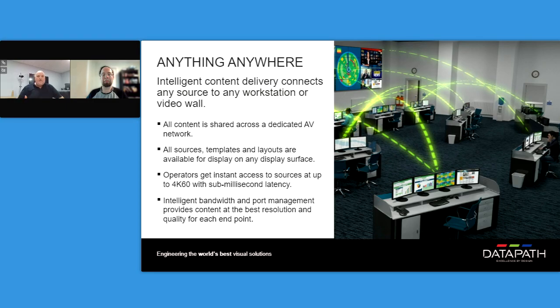As part of that automation, Atria Events can listen for things. Within Atria, one of the things it can listen for is whether one of the cables has come out of the capture card in our video wall controller, or a source machine has gone offline. We will listen for a no signal event, and then we can respond to it. And that response could be send an email, send a message, put a description on screen for the operator to see or the administrator to see.